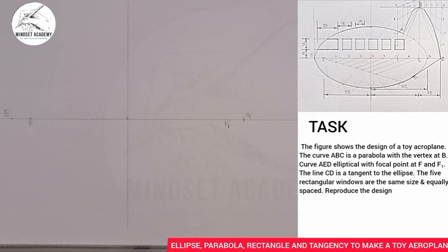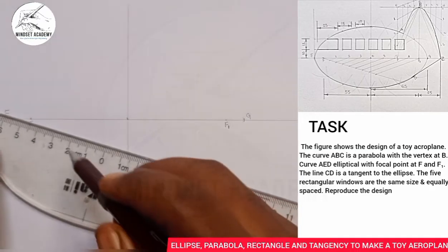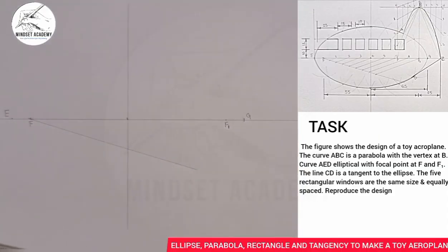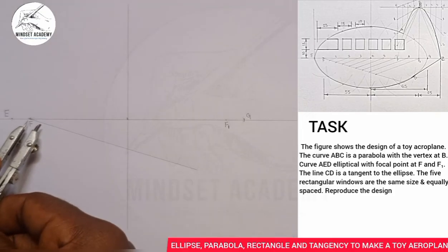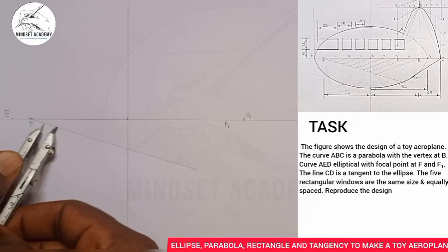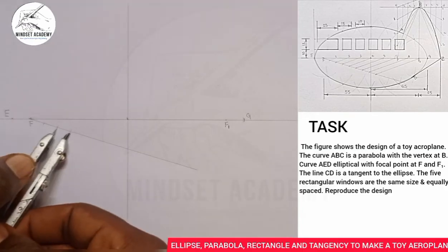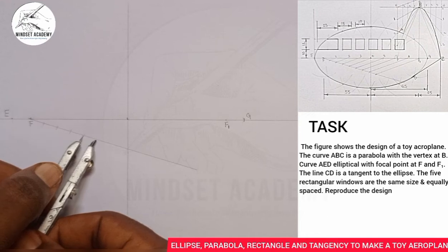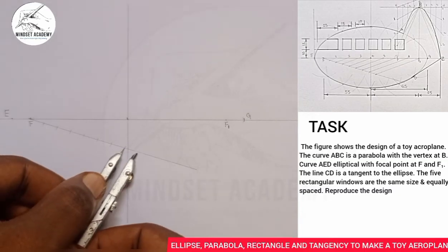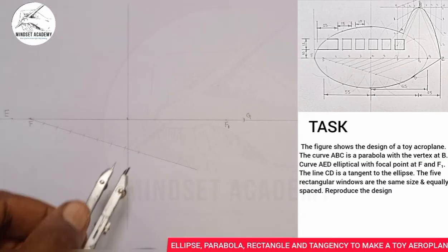So I'll use my line division method to accomplish that, right? I will just draw an inclined line from this point F. I'll draw it outward this way. Can you see that? And I'm going to mark 8 different points on that line starting from F. So this will be 1, 2, 3, 4, 5, 6, 7, 8. Can you see that?